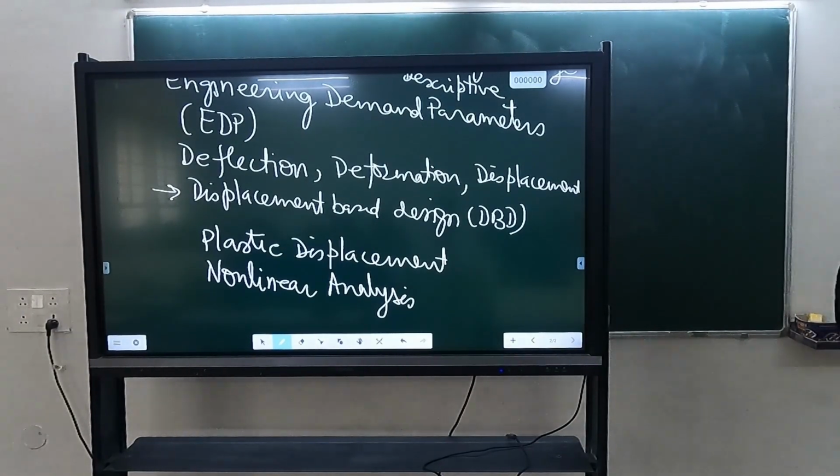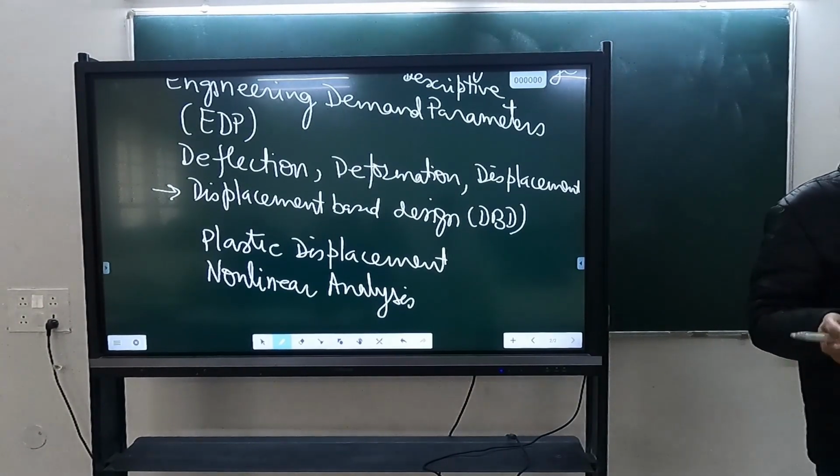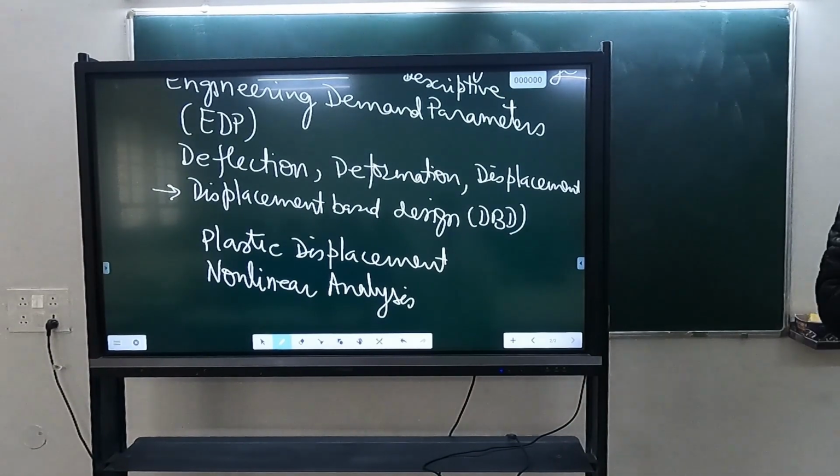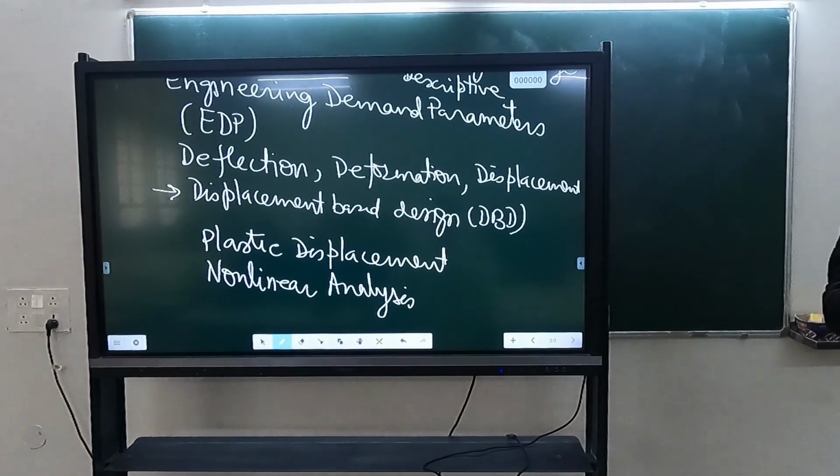Okay. So far you have been exposed to linear behavior of structures. You know how to calculate the linear displacement of any complex structure. You have done classical methods in your graduation, how to calculate elastic displacement. Then you learned the finite element method, where we also did matrix analysis. So you know how to calculate the elastic displacement of a structure. What we have to extend is how to calculate the displacement post-yield, when this linear methodology is not valid.